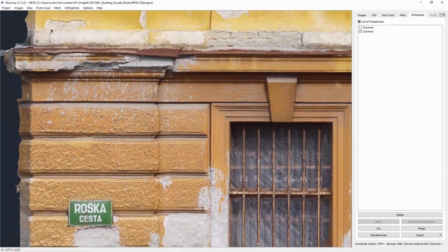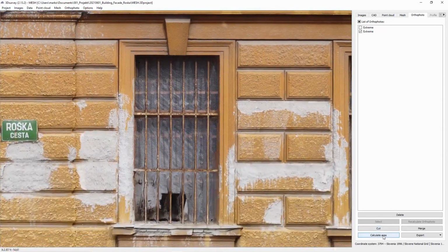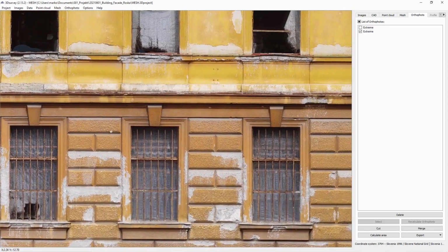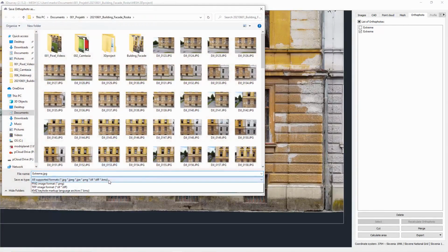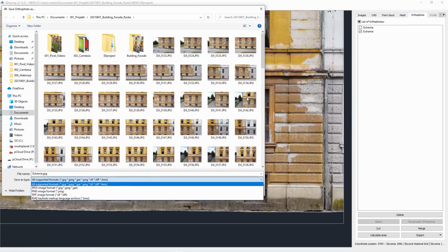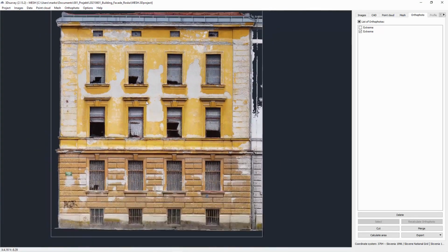It's really nicely visible, and in case we need to measure any distance here, for example, if we would like to calculate area from this specific window, we can easily click 4 points on the orthophoto and we have the area, 2.58 meters and so on. Or if you'd like to export this orthophoto as, let's say, a KMZ, JPEG or TIFF file to import it to AutoCAD or similar CAD software and draw out the CAD lines or anything like that, you could easily do it.